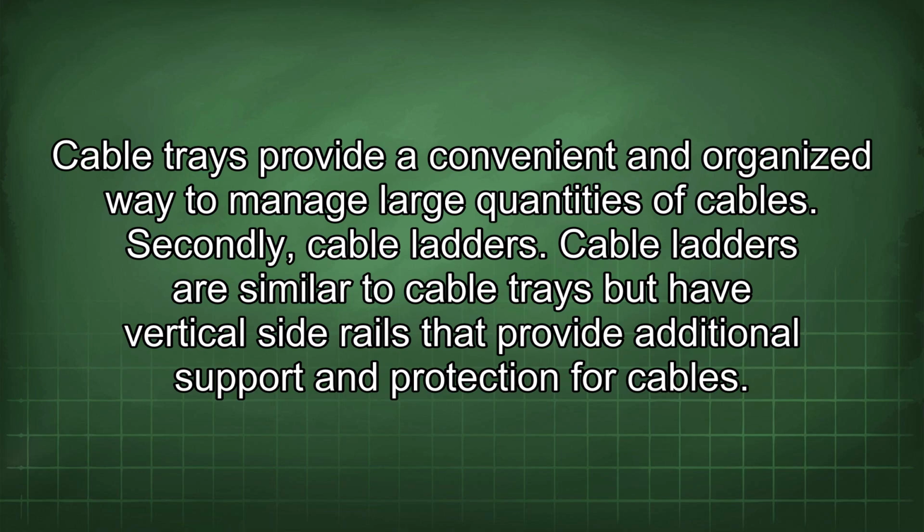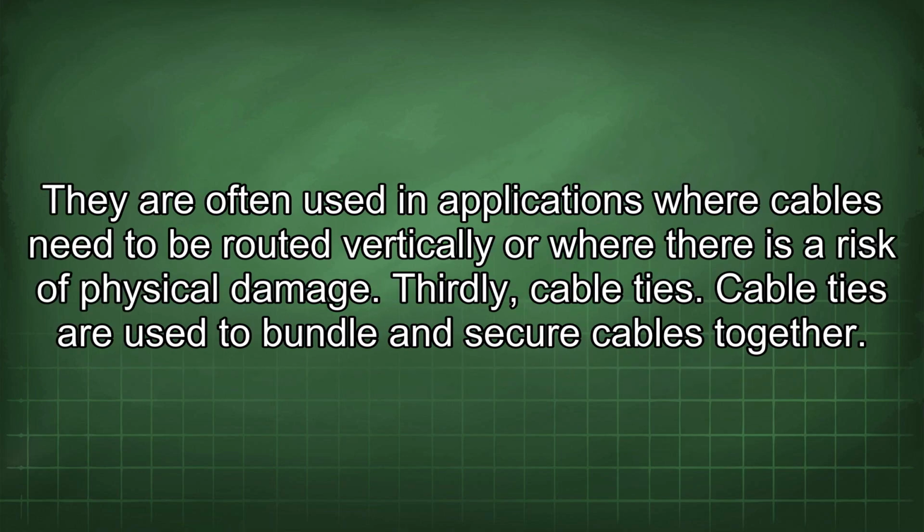Secondly, cable ladders. Cable ladders are similar to cable trays but have vertical side rails that provide additional support and protection for cables. They are often used in applications where cables need to be routed vertically or where there is a risk of physical damage.